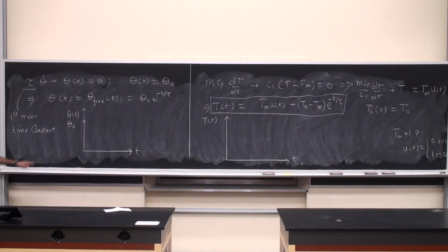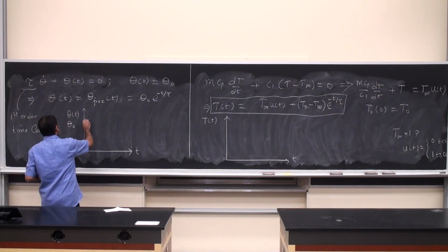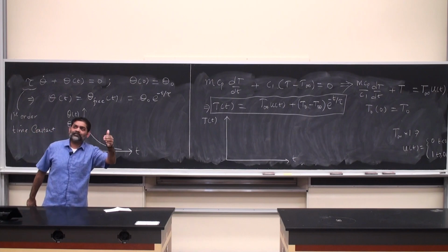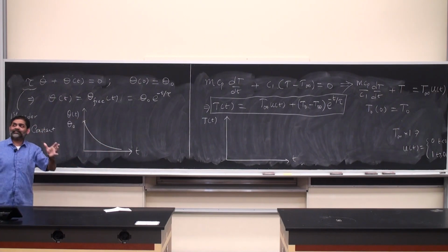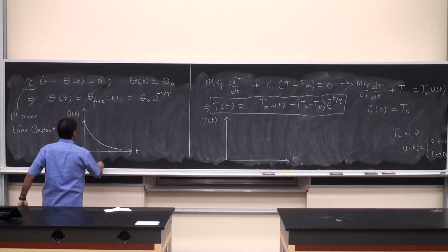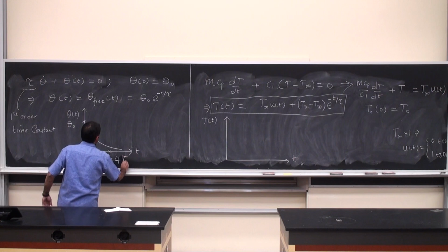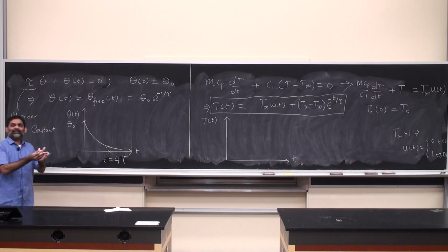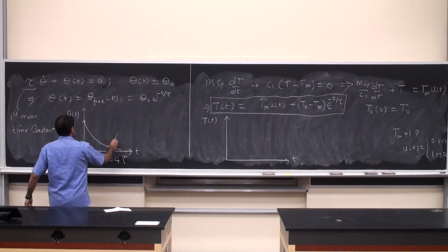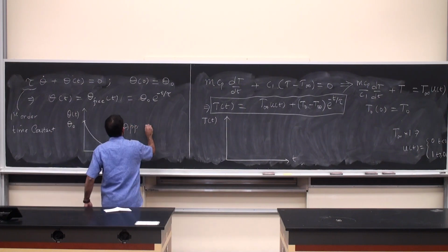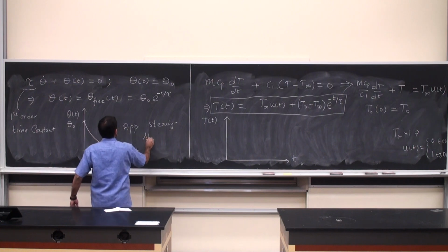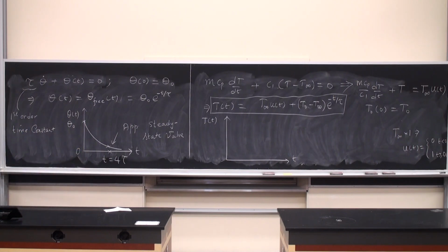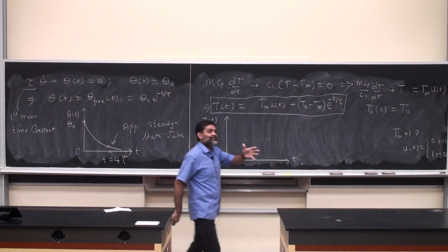Please check here. So I start off with theta naught, and the free response just decays down, as you can see, and we had a special value for the time constant at which the system appropriately reaches steady state, and that is 4 times the time constant. So when t is 4 times tau, the system is more or less at steady state. Any other decline in the system's value is not that appreciable. So this is approximately the steady state value, which is 0 in this case. So the temperature difference between the temperature of the body and the temperature of the ambient reaches 0.